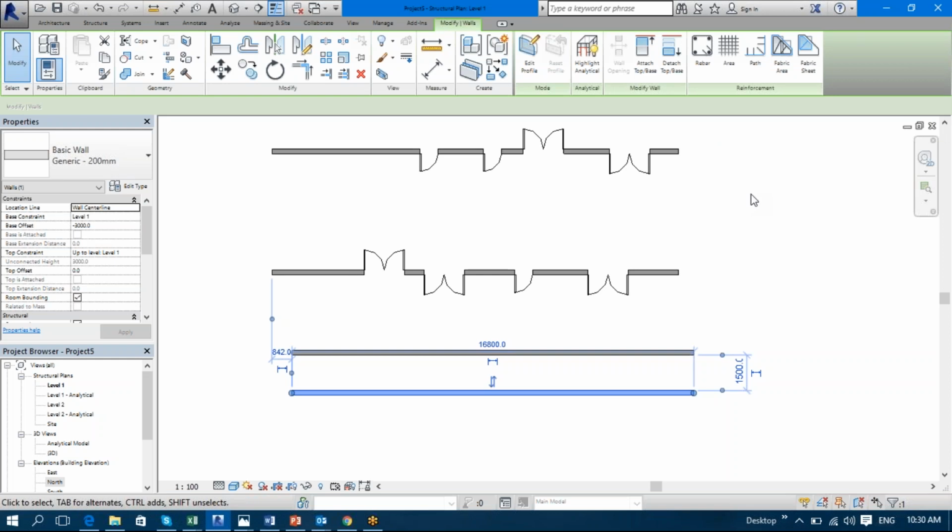and all those stuff. And then we're going to have this wall exported directly to IDAT precast link, which will create different panels out of it. And then we have to export that precast link into this AutoCAD CCAD link. And out of that we're going to create the shop drawings, and then again import it to Revit, and then from Revit we can create XML files. Okay, we'll tell you about a lot of this.